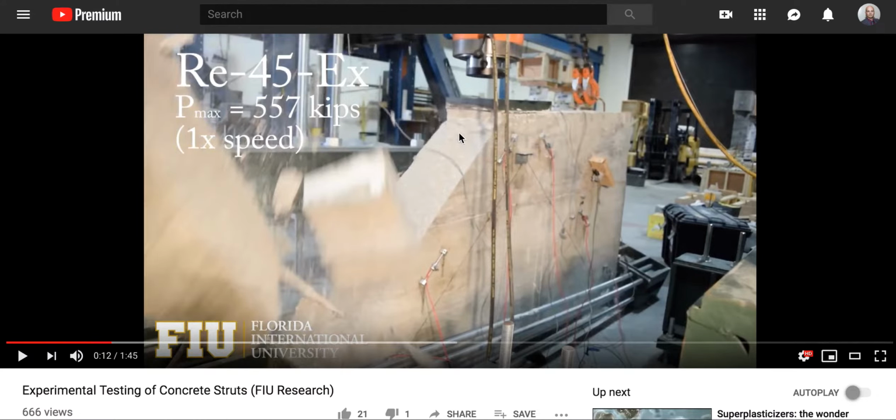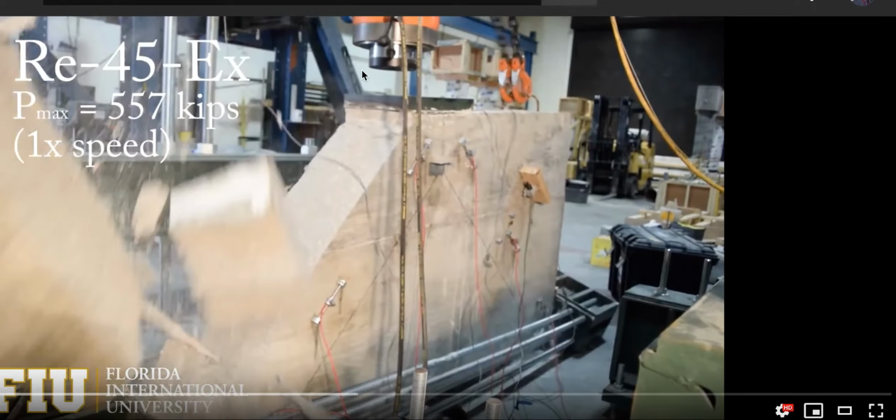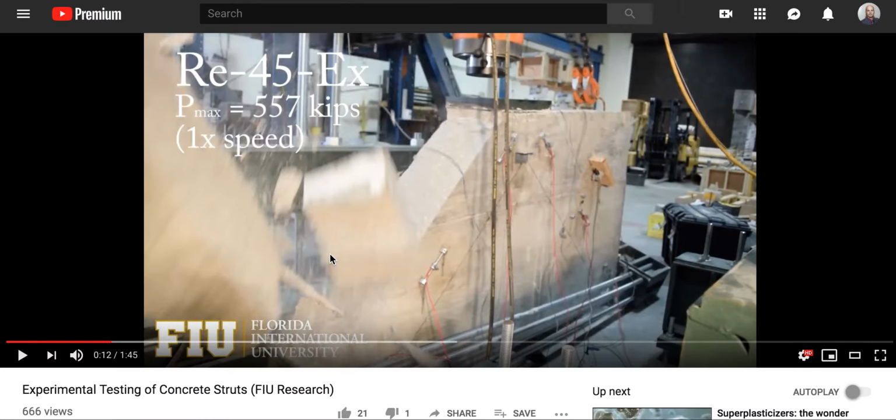They just were so concerned about the end results of the failure, whereas I'm looking at it as, well, when did the 45 start? I always find these 45s almost always never starting at the very top. They always start somewhere down into the beam and then directional. I don't see any reinforcement or anything else. Looks like a beautiful piece of concrete, and let's move on. I'll give you one more shot at that.